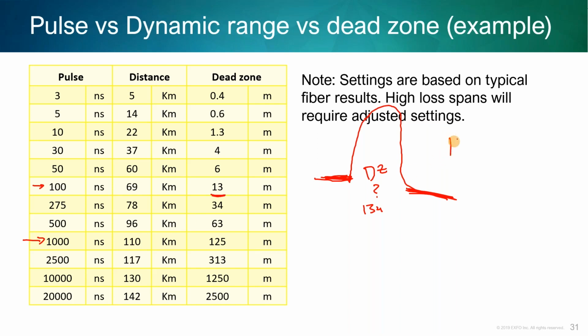I recommend 1650 nanometers because of XGS-PON, which sits at 1577. So you want to have some sort of distance between the two. We have what we call in-service OTDRs that will filter out the operating wavelengths, so it doesn't get into the sensor of the detector of the OTDR, and then test downstream live. So we do have those. Now, as far as analyzing the results, it's the same. It's all exactly the same.